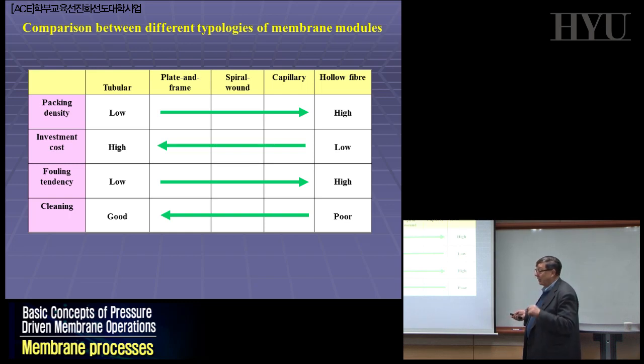Today, Toyobo is the only one in the world still doing it, because using hollow fibers, you have to pre-treat all the solution very significantly, because there is always something going in and plugging the front. With time, you just make a deposit in front or inside. So it is a big mistake to use the wrong fibers for something where the cleaning is complicated.